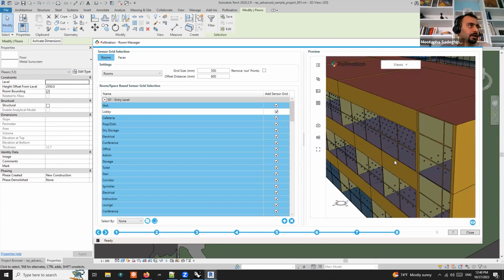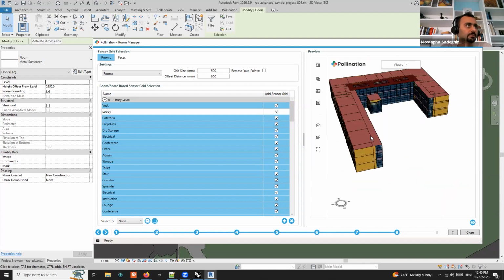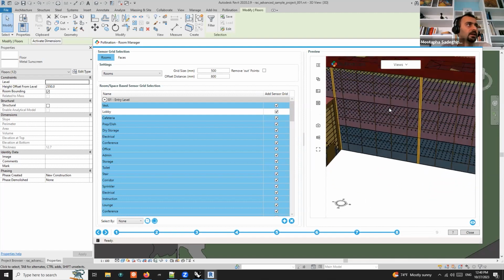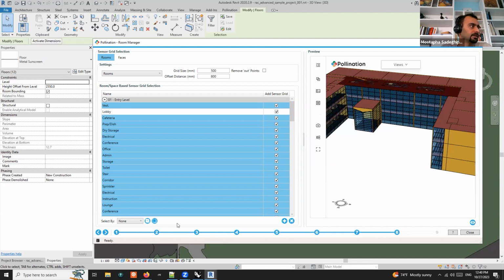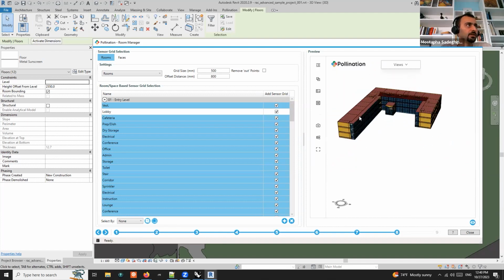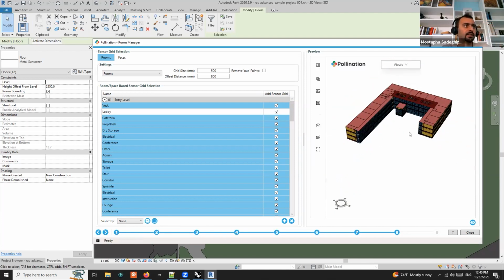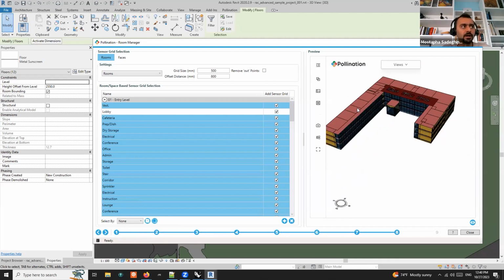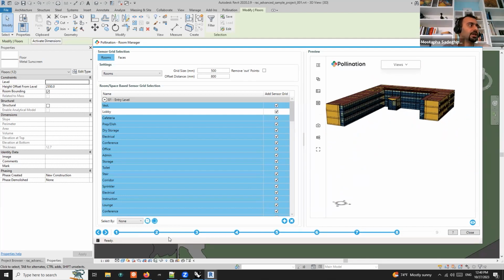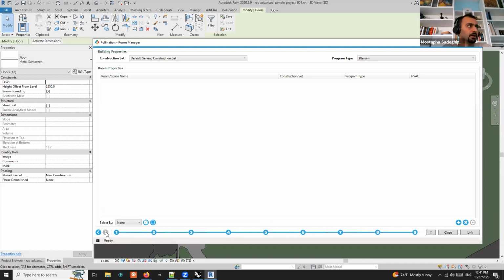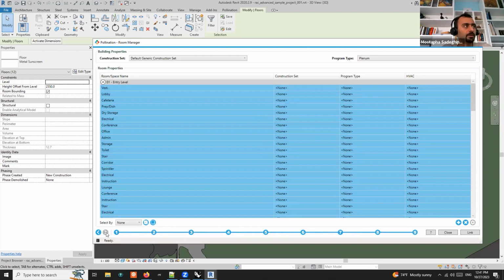Here you go. So you can actually check the sensor grids too to make sure the size makes sense. The parts that need sensor grids get sensor grids. And for example, you see there are ceilings here instead of roof, right? Because I didn't set that property for exposed, and the Rhino plugin couldn't figure it out by itself. But again, for this daylight study, it's not going to make a major change. So I'm not going to fix that.